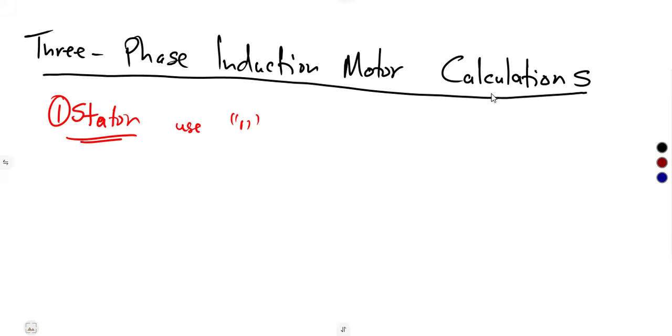All right, so in our stator, the calculations that will be important, remember, we talked about the issue of being three-phase. So definitely it will affect the voltages in star and in delta. Those are the ones that we can talk about. In a star connection, remember that the line voltage is equal to the square root of 3 times the phase voltage. So in our case, we are talking about the stator using the subscript 1, so we're just going to call it 1 and 1 here.